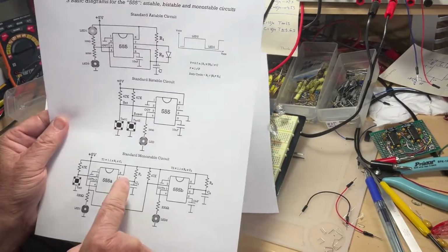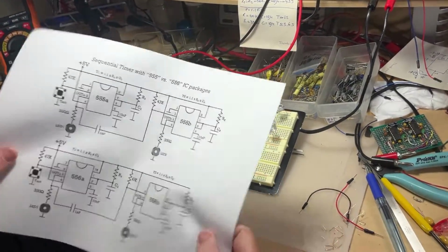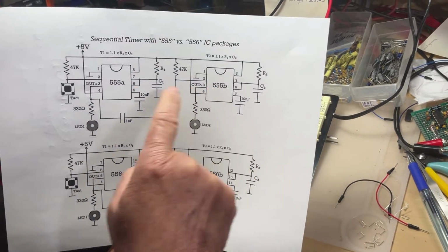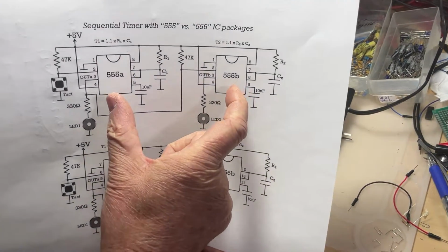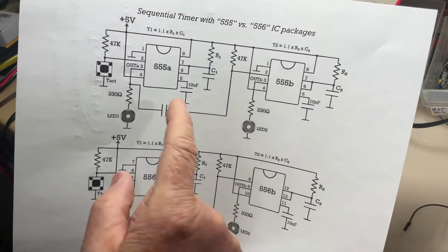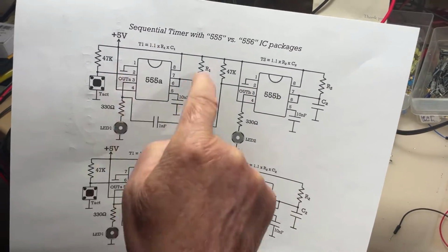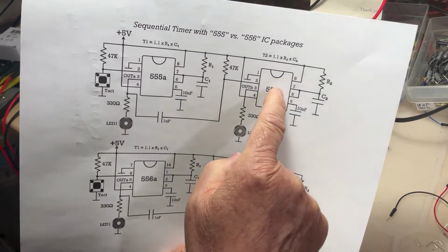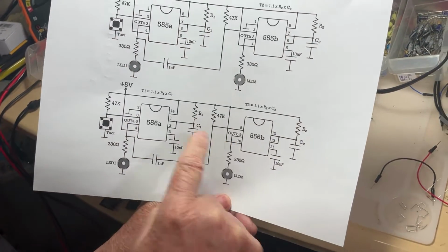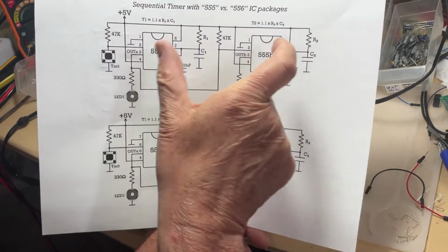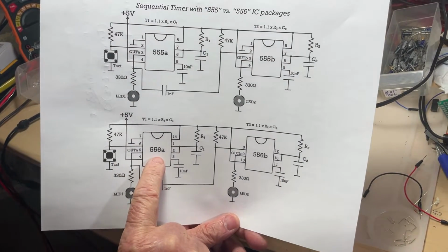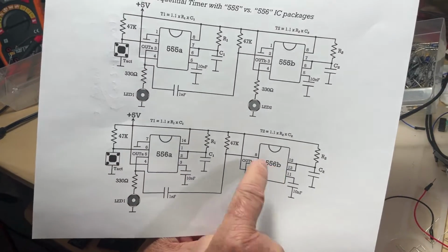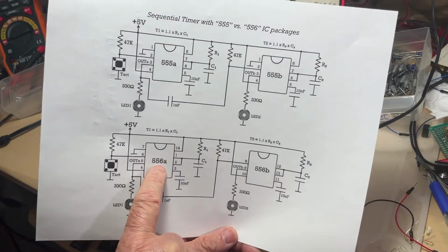But because I want to focus on the monostable, what am I going to do? I prepared for you a diagram where the 555, like in the original diagram of the application, both of them being connected together, you have the pin out. Both of them have the same pin out because the packages are identical. But what's nicer, what I've made here in the bottom, I translated this by using one package 556. The 556 again contains two 555s in the same package. And here is also the pin assignment, but for the 556.